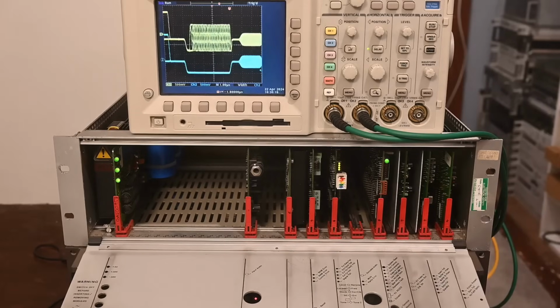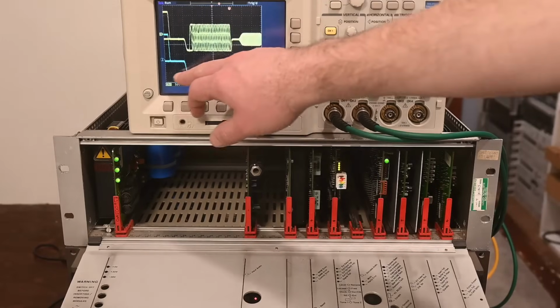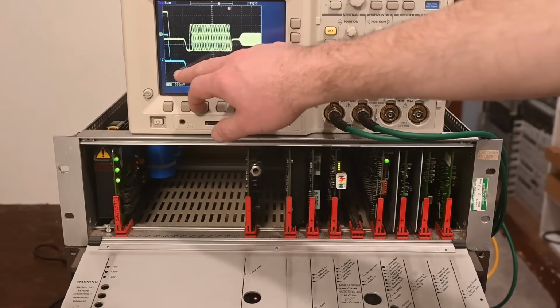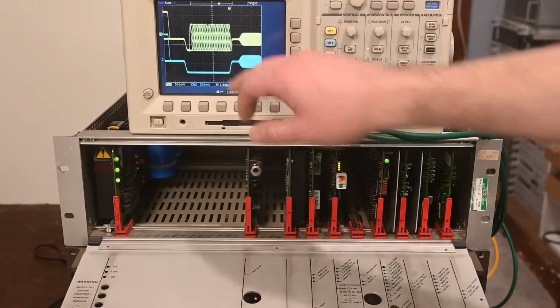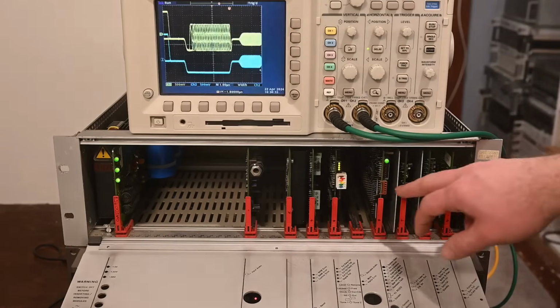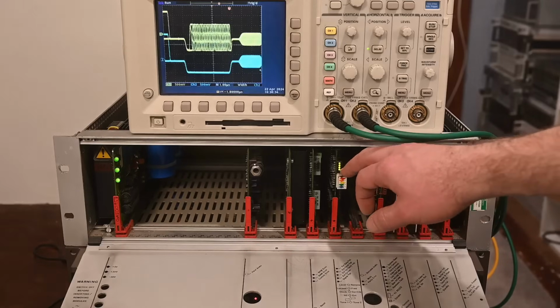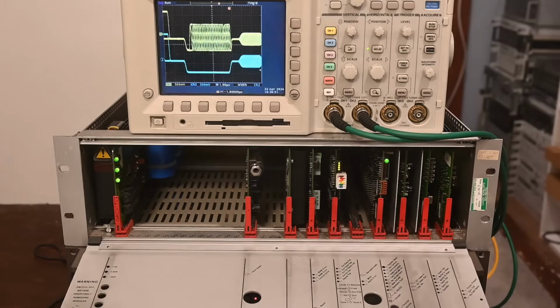And straight away we see the SIS data burst on the oscilloscope there, and the inputs to the SIS coder. That's the horizontal synchronization period, and that's of course it with the data burst inserted. And looking at all the LEDs, everything is switched off. We just have these 4 warnings over here saying that there's no external NICAM. Anyway, otherwise we're basically in operation, and we can head over to the transmitter and have a look what's going on over there.